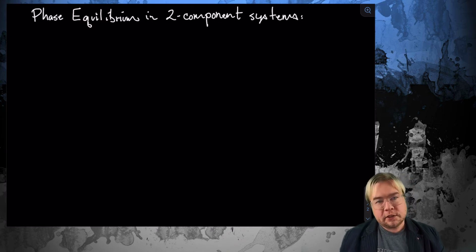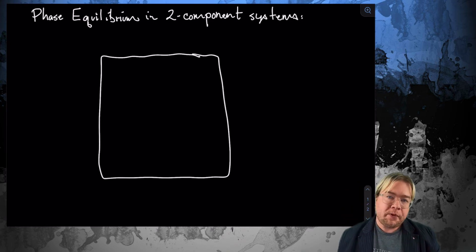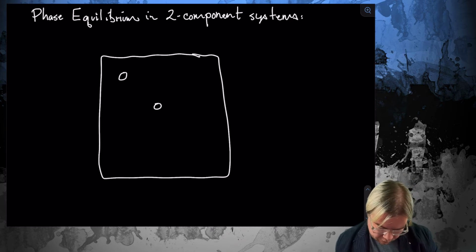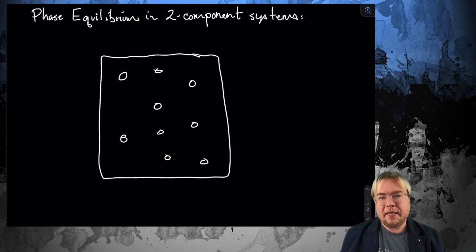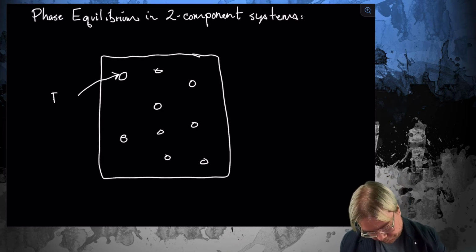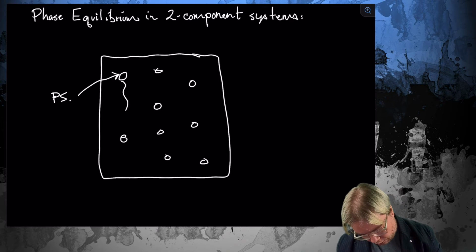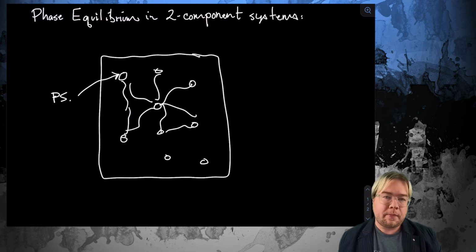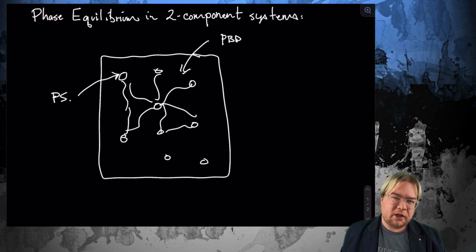So if you were to zoom in on the soles of your shoes and look at what the structure of that material is, what you would find is you've got little spherical domains that are distributed throughout the material. And these are the hard polystyrene parts. They impart some strong mechanical properties to the material, but you also want them flexible and rubbery. And so these hard polystyrene inclusions are linked together by polybutadiene chains.